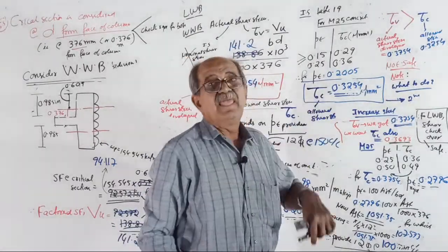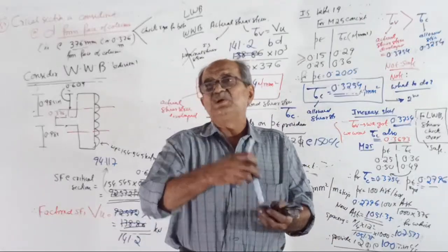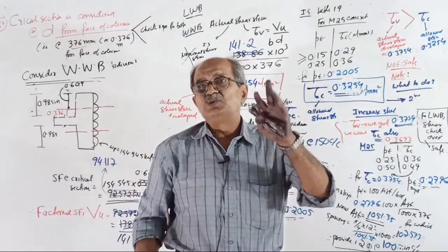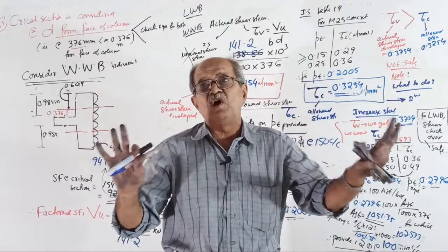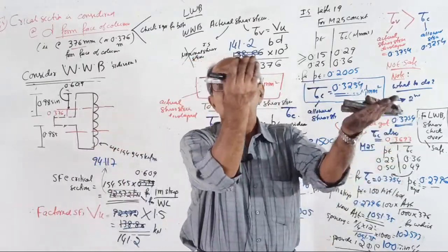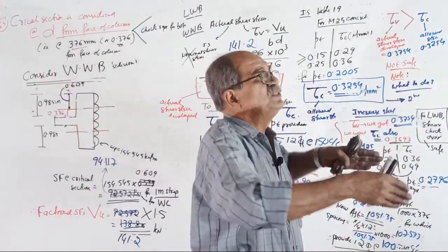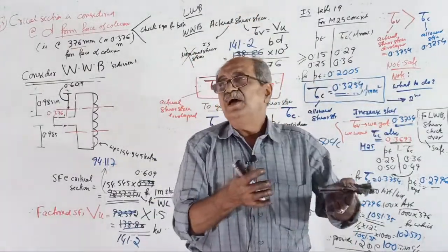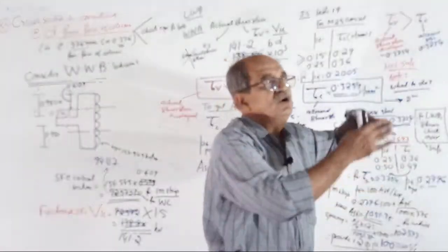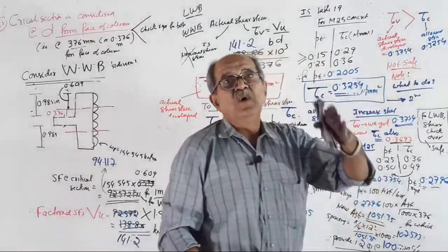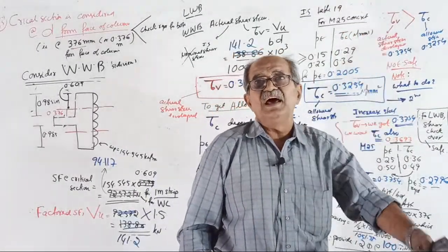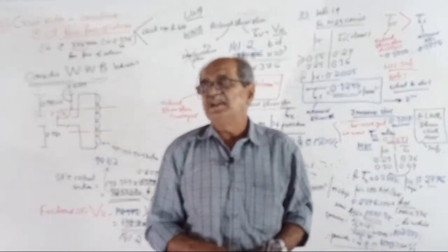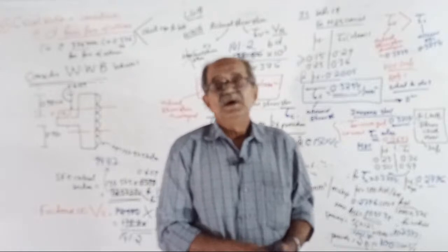This question, column subjected to only axial load, the purpose is to understand all the concepts of footing, like lengthwise bending, widthwise bending, then punching shear, how it comes, how to find steel for this bending, how to check for one-way shear, and how to check for one-way shear the other way. The purpose is to understand the basic concept.